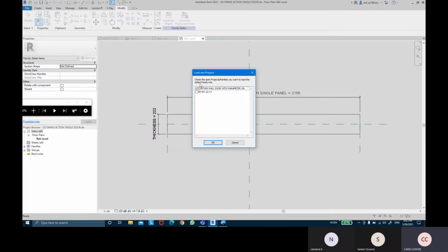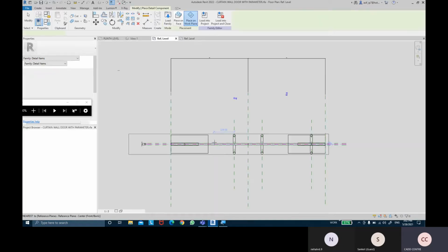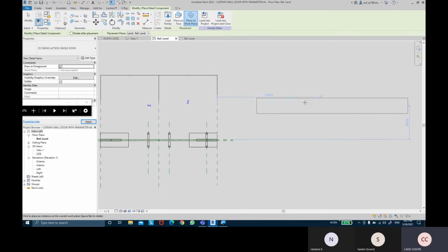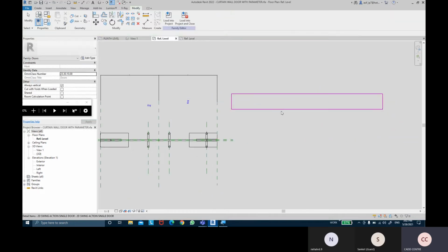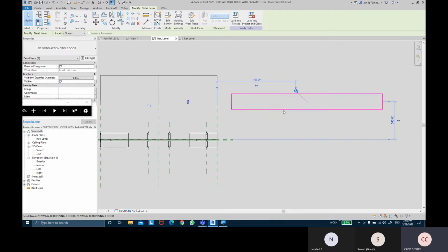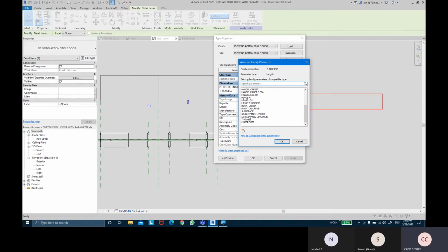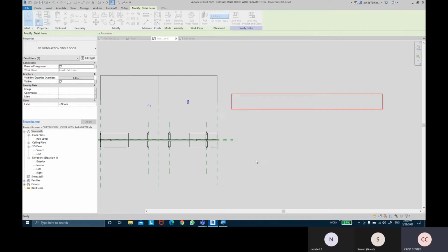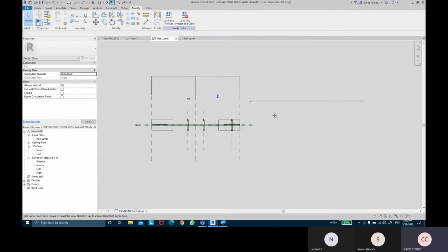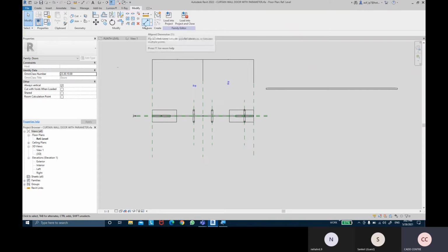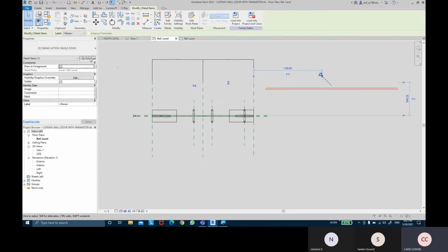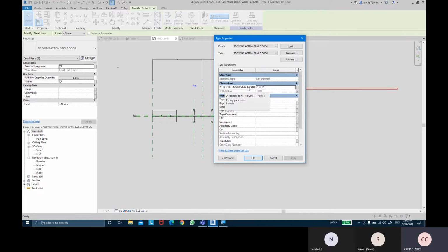And you can load this into our project, into that family. Surely it does get loaded this time. Only thing is that thickness does not match, so we're going to select this, come into the edit type and match thickness with thickness, and the 2D door length should go with the 2D door length single panel.